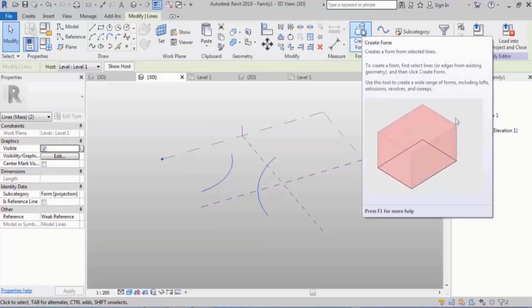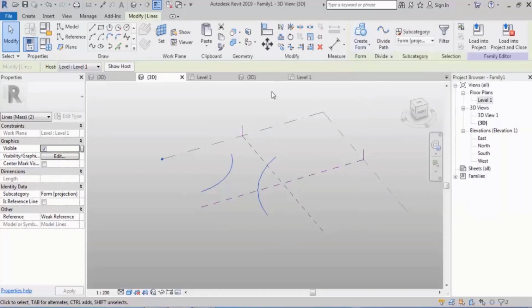I give you options. The first option, they will be extruded one by one. Option 2, they will be connected and then extruded. Option 3, one of them will rotate around that, it's revolve. Option 4, they will be connected and they will turn into a sheet. What's the answer? Could you find that? That's right. They will be connected. Option 4, and they will create a shell, a sheet, right?